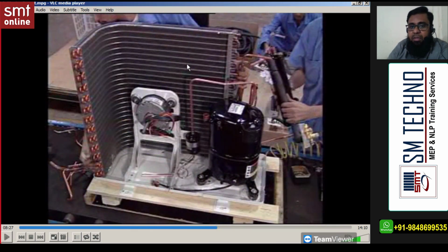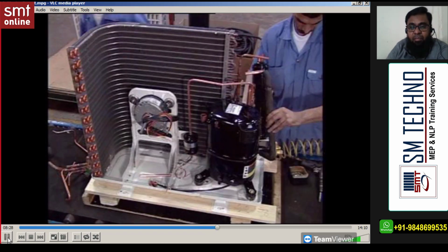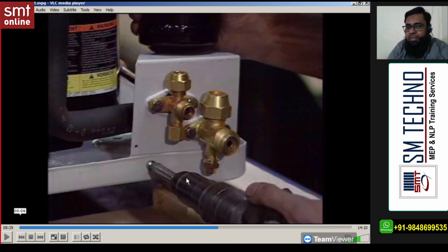You see this L shape is what? The condenser. It can be L shape, it can be U shape, it can be round, depending on the model. And you can find the fins also. So this is the condenser. The compressor and condenser are the major components in the outdoor unit. Copper tubes and coil guards are added. Can you find the valve?